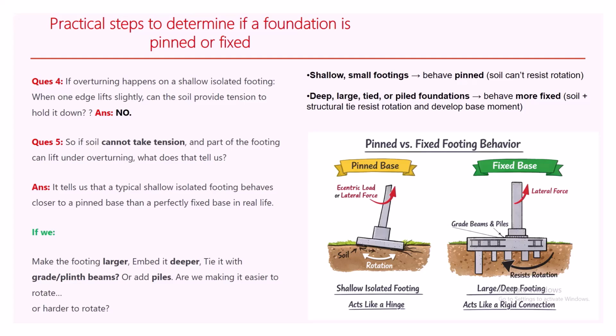Because from the soil test report, you're able to know whether you have clay or loose sand. Clay automatically deforms, and that deformation makes it pin supported. So by the soil test report, you're able to understand how your foundation is going to interact with the soil, and by so doing, you're able to know when to provide plinth beams or not. So it's based on your own judgment.